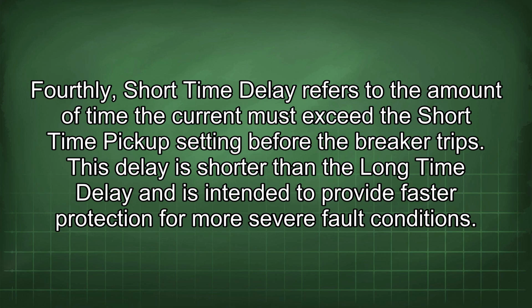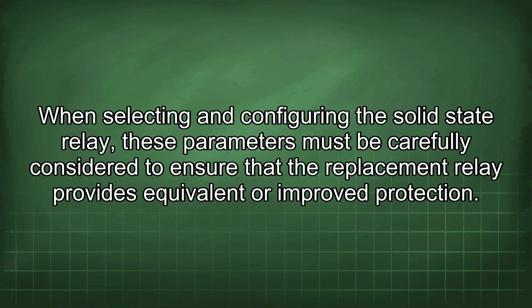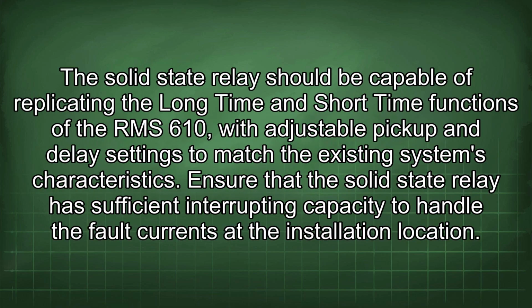When selecting and configuring the solid-state relay, these parameters must be carefully considered to ensure that the replacement relay provides equivalent or improved protection. The solid-state relay should be capable of replicating the long-time and short-time functions of the RMS 610 with adjustable pickup and delay settings to match the existing system's characteristics.